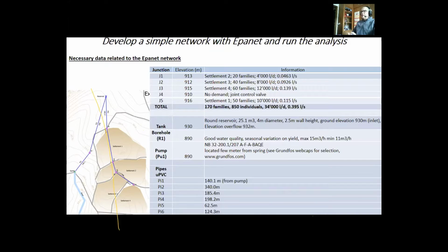The tank can be existing. In that case, you need to give the real dimensions of the tank, or maybe the tank is new, so you have to estimate at the beginning how big the tank should be. It can be that you already have a tank in storage, an Oxfam tank, or maybe bladders. Depending on what you have, you might already have the dimensions, or you might have to construct the tank. And then you have the borehole or the source, called in that case a reservoir, the lake to be clear. And for that you just need the elevation.